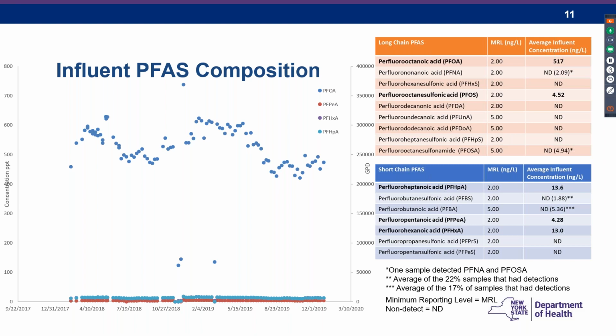We were able to take the monthly operations report from the system and take a look at what the demands, or not the demands, but what the processed water was. And when you overlay that, so that would be this plot here, when you overlay that with the concentration, there's pretty good agreement between increased usage, increased pumping, and an increased concentration.